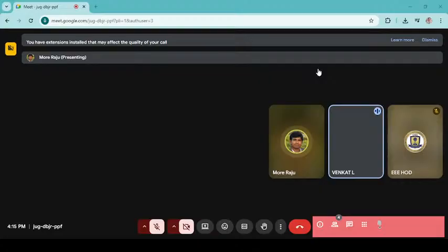So you see that a synchronous motor can be run as a salient pole synchronous motor with the field winding energized, and as a synchronous reluctance motor with the field winding de-energized, meaning the field winding is not considered. So the synchronous motor can then be considered as a variable reluctance motor.